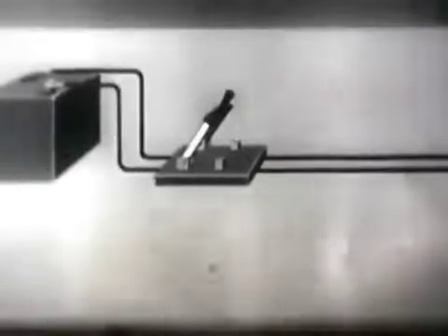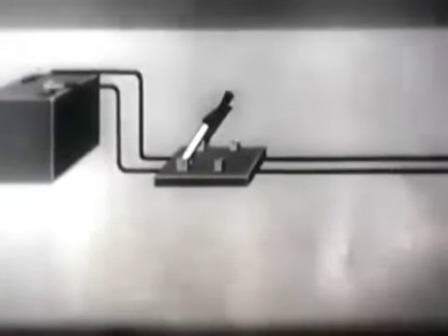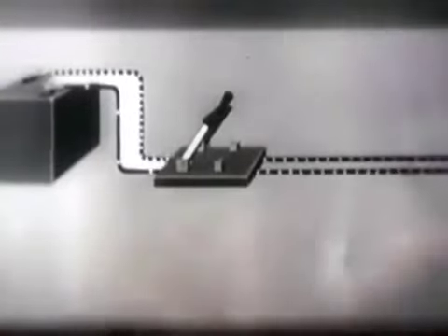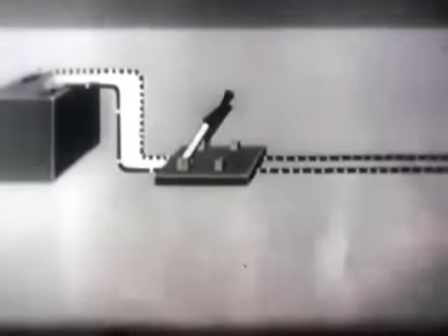Let's dream up a theoretical transmission line and study its behavior. The two wires will be endless, or infinite, in length. Now let's connect a source of electrical energy at some point. Even with our switch open, we know a voltage exists between the terminals of the battery and up to the open switch.